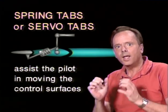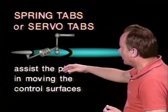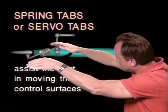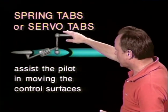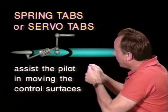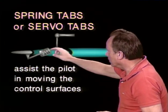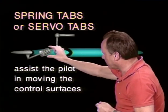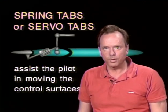Now both of these help the pilot, or assist the pilot, in moving the control surfaces. The way a servo tab works, if you want to move, for instance, the elevator up, it goes down and helps provide the force to move the elevator up. A spring tab is very similar. It would do the same thing, but a spring tab has a spring in it so that very little movement by the pilot doesn't wind up having the tab helping you. Then when the spring gets a little pressure on it, the tab comes and helps you. They're very similar devices, but they both assist the pilot in moving control surfaces, and that's what you need to know for the written exam.